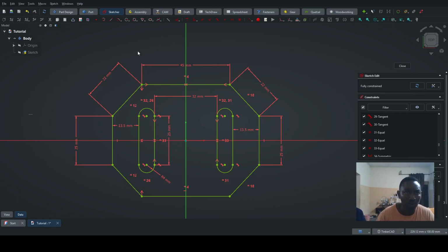So if I go to display and decide on how smooth I want it to be by changing anti-aliasing and things like that, all sorts of things. Go to my UI, change colors. I can change colors. Presently, I'm using a theme. That is why mine looks like that. If I choose FreeCAD, it will look exactly how yours look when you started. You can change for navigation too. You can change all sorts of things here.